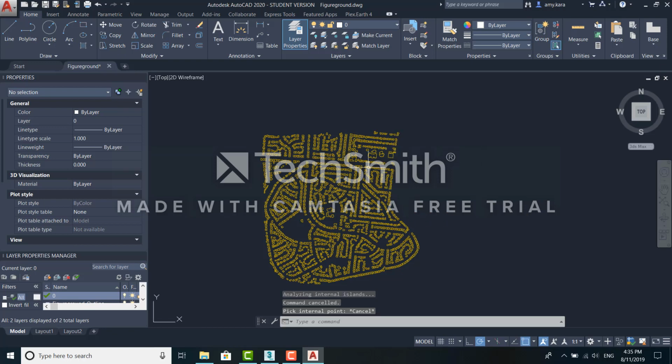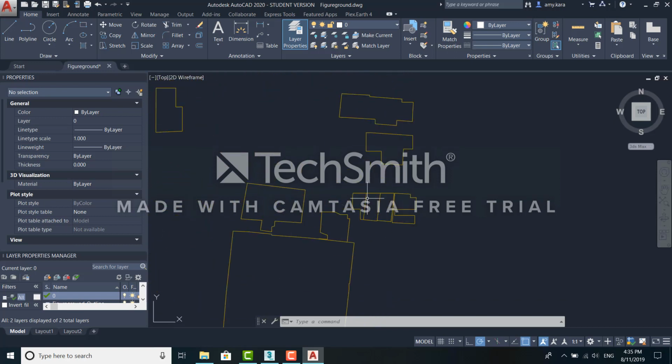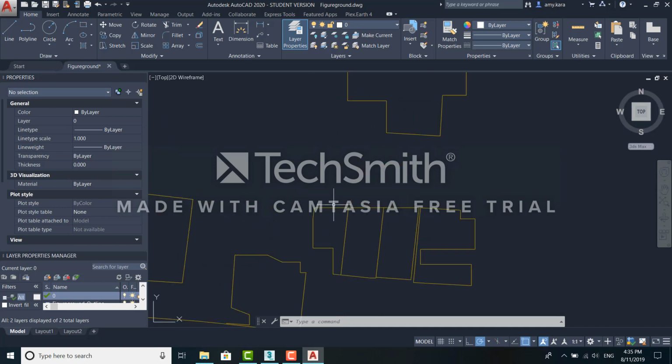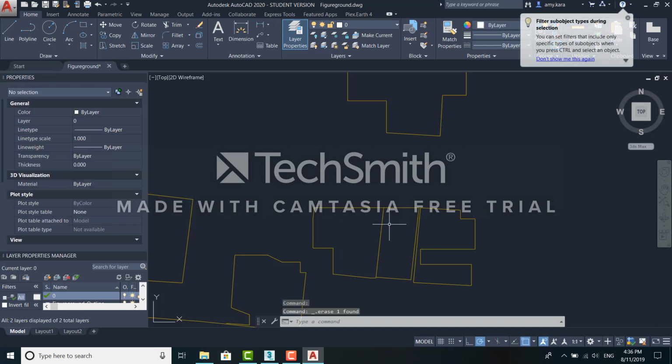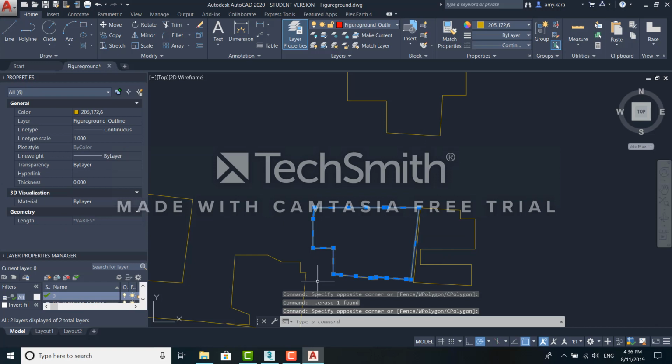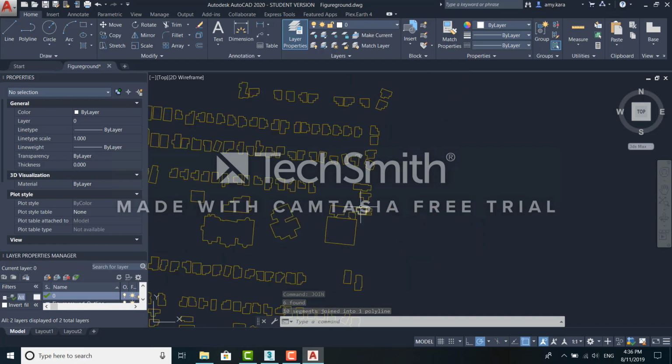So the other alternative is, if we just exit that, the other option is to actually, as you can see, there's an enclosed one here, but these ones are not. So in order to get this line out of this enclosed to create an overall closed building envelope polyline, we can hold down Control, and this will allow us to select just this line within the polyline. We can just press delete and then join that to create one polyline entity.